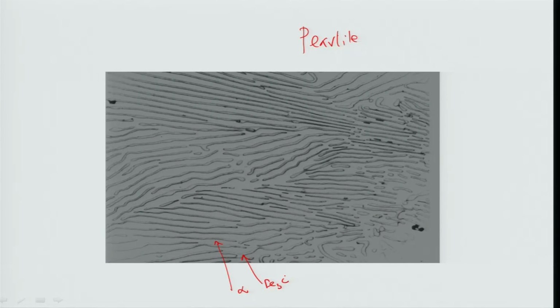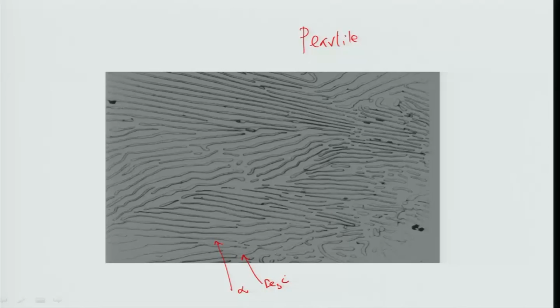So, the real microstructure will be like this, it looks exactly like a eutectic microstructure. A eutectic microstructure will have lamellae of alpha and beta phases. Similarly, these are called alpha lamellae and Fe3C lamellae. All these dark colored things which I am drawing are Fe3C, the white thing is alpha. This is actually a mixture of a very hard phase, Fe3C, with alpha, which is a ductile phase, and because of this mixture, which is known as an in situ composite, steel has wonderful mechanical and physical properties.